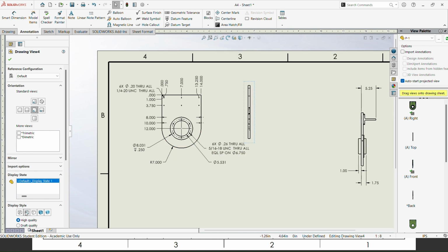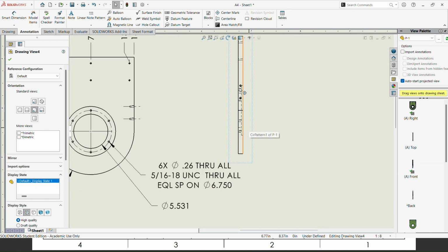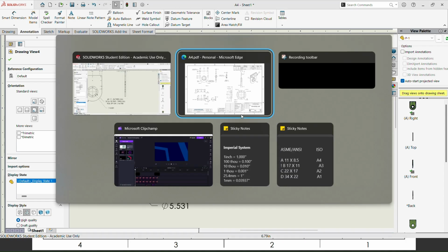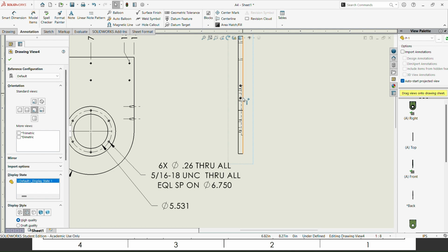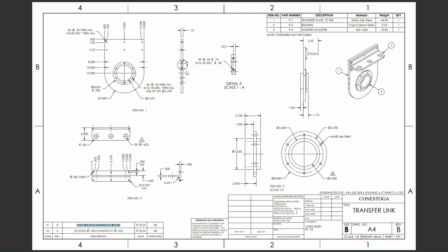You can see the hidden lines. You can see it's not just the way we want. So we can see the walls are here, but in the opposite direction. So I am selecting this view, that is back view. So now it's okay. So what I'm going to do is I'm taking this part out, a detailed view. This is a very small portion of this drawing, so it's very difficult to see. So I'm going to use the detail view function to zoom this out.